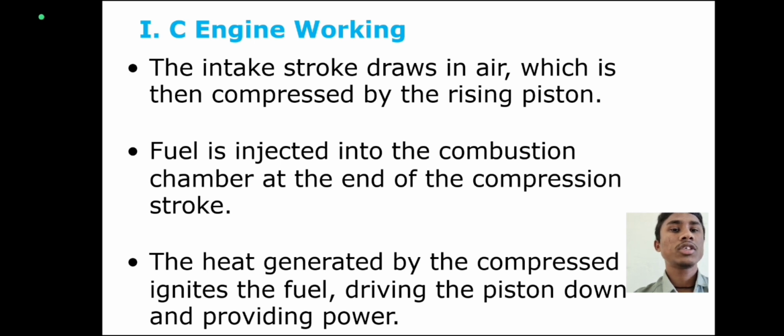Internal combustion engine working: the intake stroke draws in air, which is then compressed by the rising piston. Fuel is injected into the combustion chamber at the end of the compression stroke. The heat generated by compression ignites the fuel, driving the piston down and providing power.